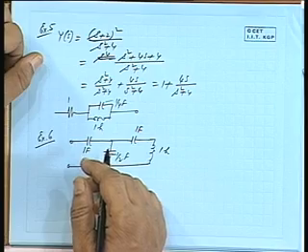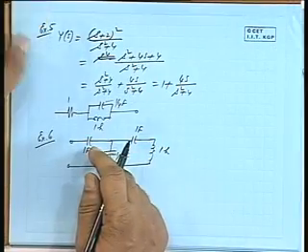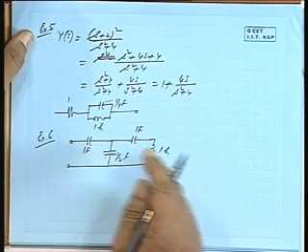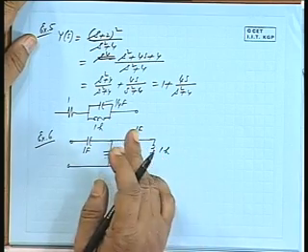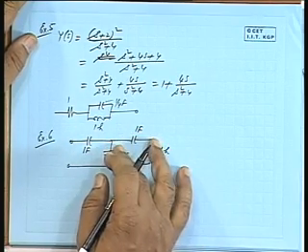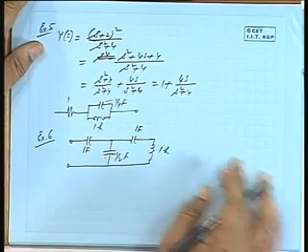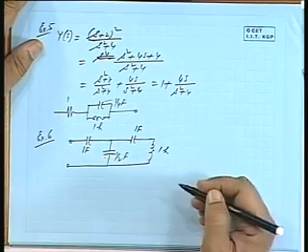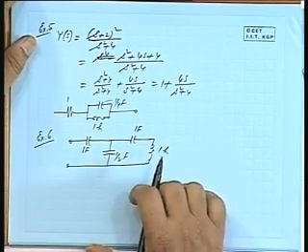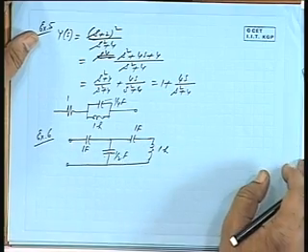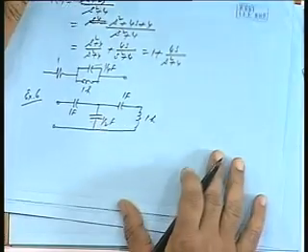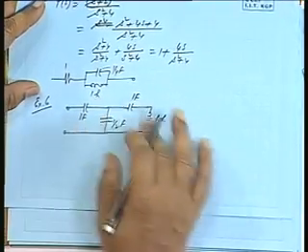Why? Because in a canonical form the difference in the type of elements will be restricted to 1, either 1 inductance, 2 capacitances or 1 capacitance. Alright. So, what will be the canonical form for this? Can you find out a canonical form for this? So, let us calculate Z(s).